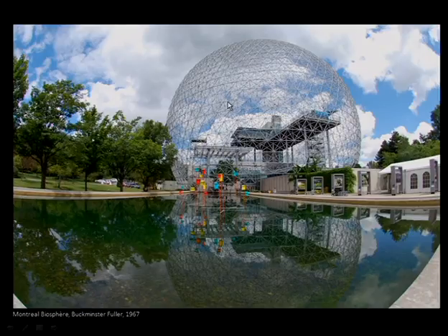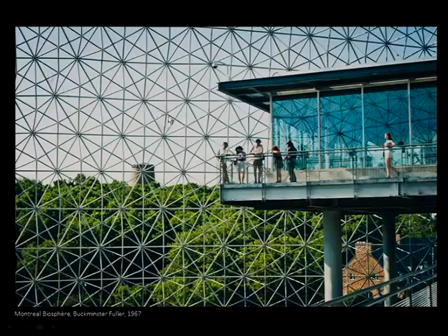And what's interesting here is that when you have all these bars, let me simplify it this way, it's like a three-dimensional truss. So it's a spatial structure, like a truss made of elements going in three different directions, and then also deformed to get the sphere. You know that the sphere can be discretized in triangles, hexagons, pentagons. And what Fuller does is exactly that, to discretize the sphere in a set of hexagons. You see them here, but then they are also extruded in other elements to create the joints and to give a bit of thickness to that structure.